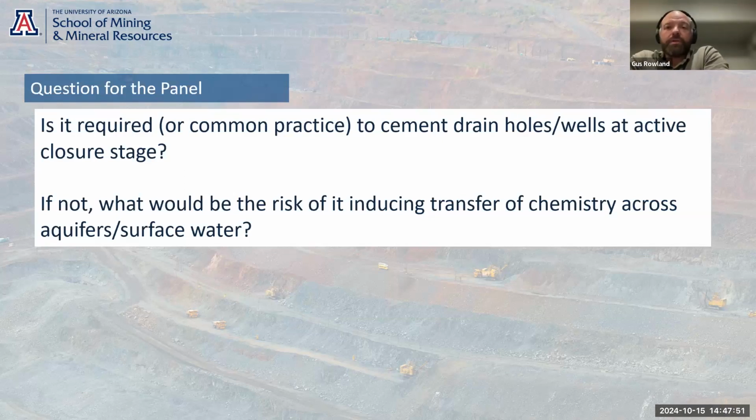Again, grouting those wells straight after exploration tends to be the best way to deal with that. Once you've moved a rig off and once you've left a hole open for long enough, you're almost certainly not going to be able to grout it after the fact.